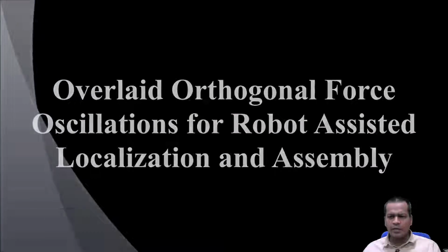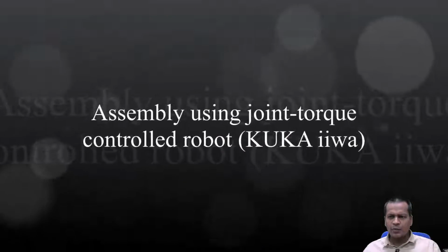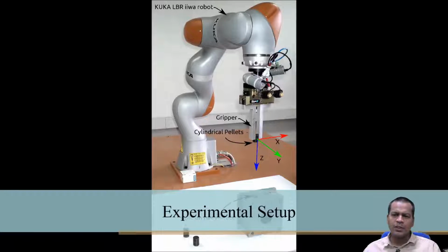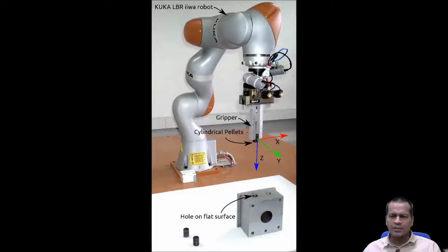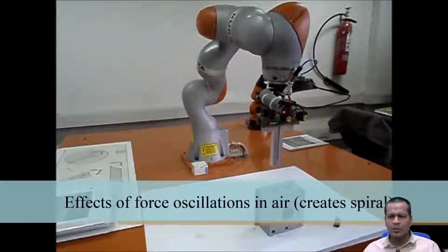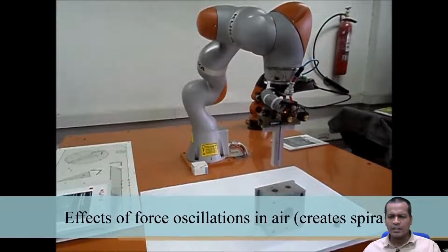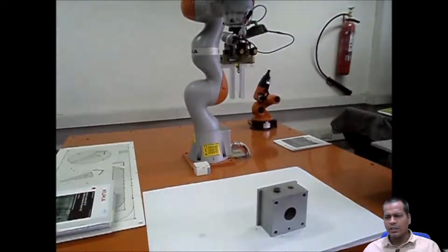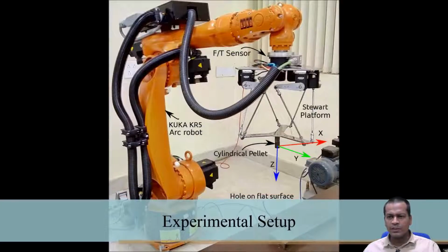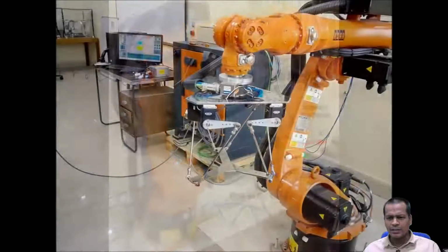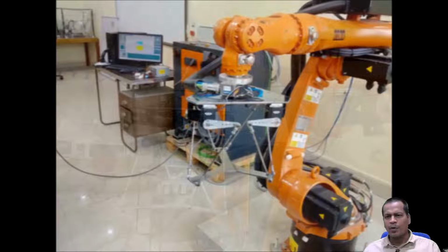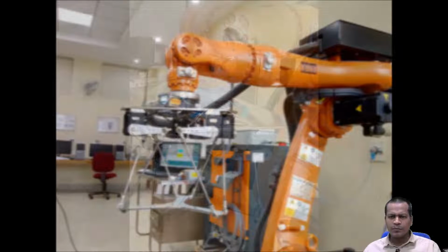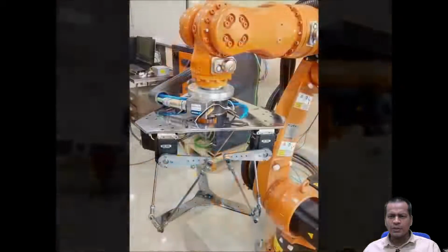So again, I used a parallel robot to do the thing which I have done with the cobot yesterday. I showed you inserting a peg in a hole through a spiral search motion. This can be done with a serial parallel combination, so that is what we did. Over here I have just attached a parallel robot on top of a serial robot. This is for micro manipulation, as I have said, and this is doable. You can fit a parallel robot on top of a serial robot.